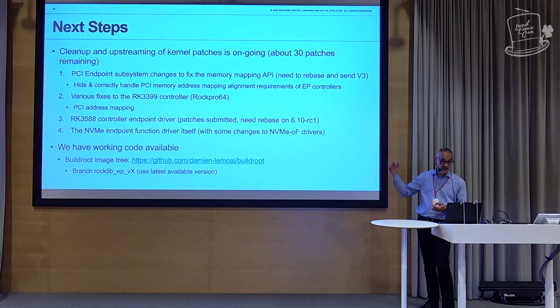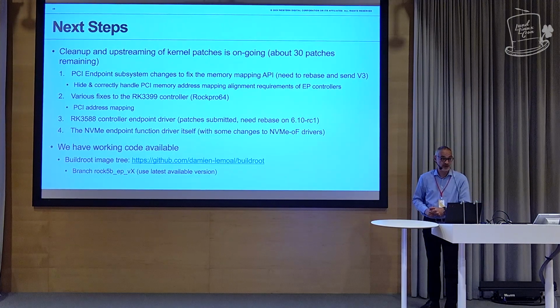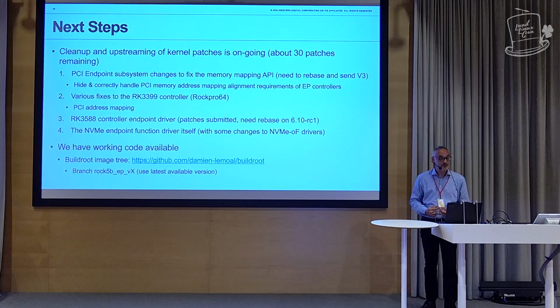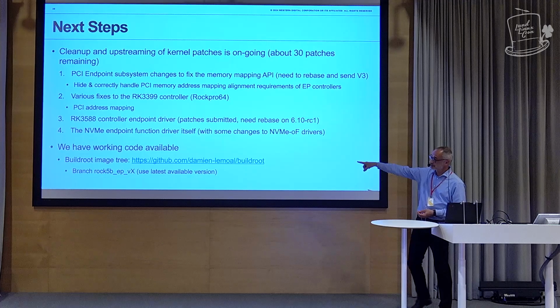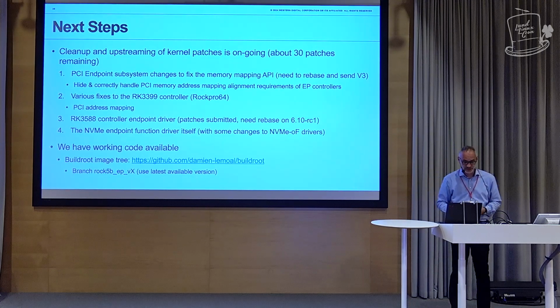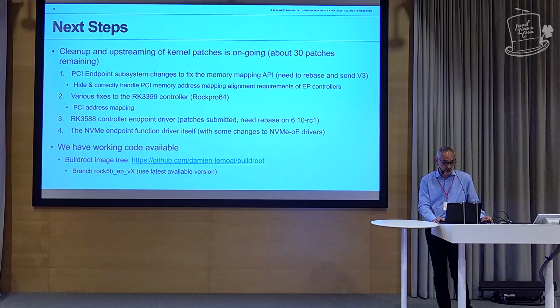Once we get all that, actually we don't even need the RK3588 endpoint driver. We can send the NVMe endpoint function driver upstream itself. We will need the PCI subsystem API changes though, because we depend on it. If you want to try this out, we have code out there on my GitHub. I have a full build tree that you can grab and just type make, and it will generate an image to put on the SD card of the board, and that will give you everything you need to run your endpoint.